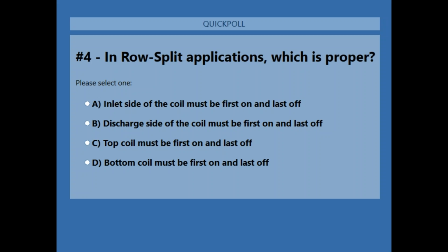If by chance you're running through a real hot attic or space, at say 100 degrees or higher, then it would be worth insulating it so we don't end up with flash gas in the liquid line. But as standard on a normal installation, no, you don't have to.